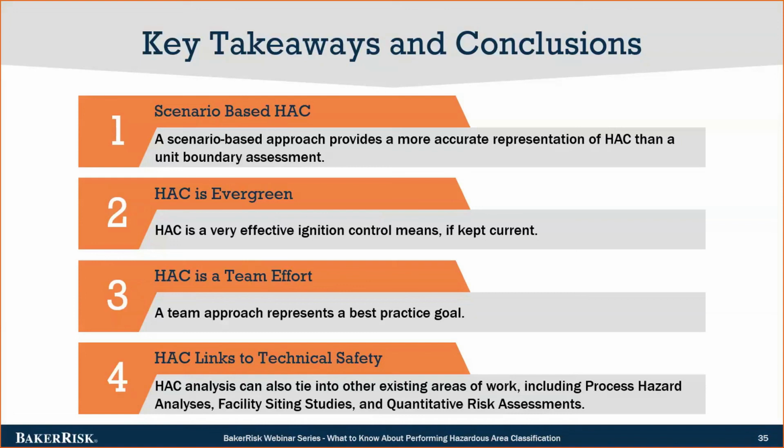Where are the areas that we're handling materials above their flash points or other areas that need to have special concerns? If we're using electrical equipment, and in most cases we are, we need to know what is that equipment that's being used. As most of you are aware, there are all kinds of motors, but not all motors are suitable for certain types of processing conditions. So you need somebody who has experience with the actual equipment that's installed. And lastly, I think you need somebody who's involved with training so that everybody can be up to speed with what exactly is entailed in the hazardous area classification.